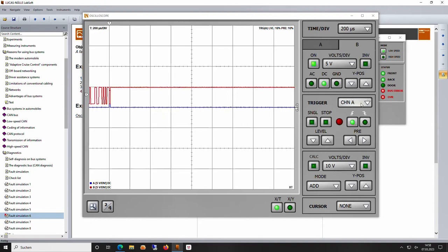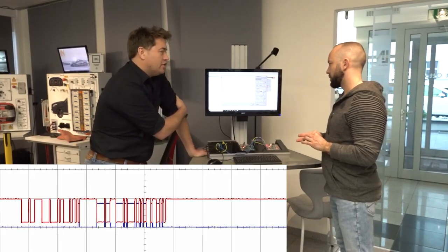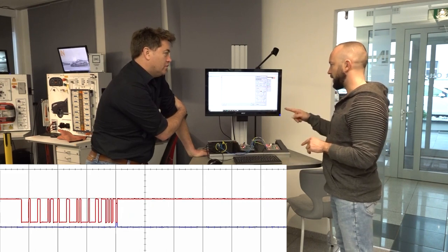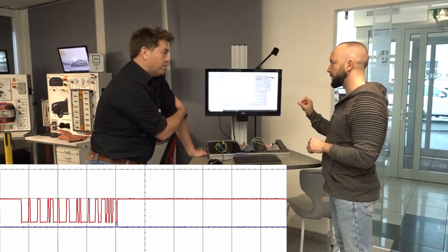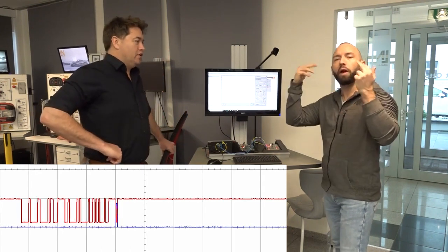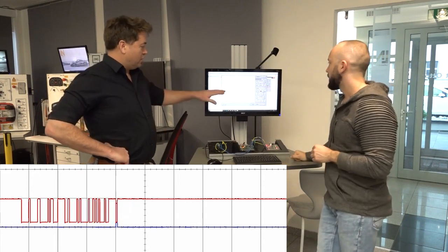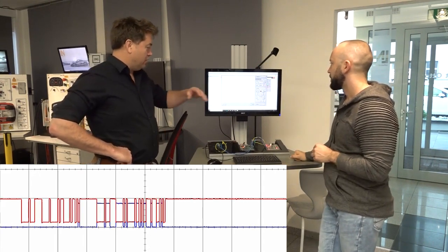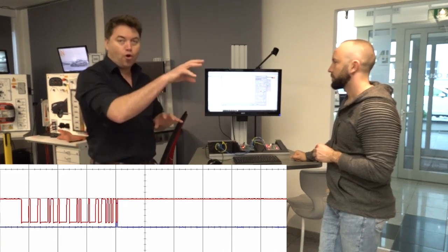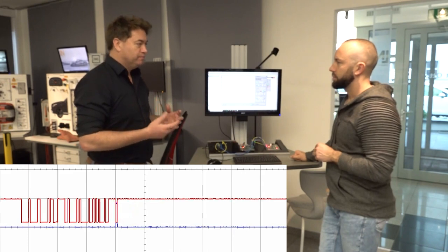This one here is also quite interesting. So this is showing that part of the CAN node has gone missing. Now this last piece, that's the acknowledge bit, is that correct? That's true. Yeah, we have the CRC and then there's the acknowledge bit, which basically says, yeah, signal not sent, but signal arrived, received, exactly. And so it was unable to, it said, yeah, we've got the signal, but it wasn't able to send the signal on. So there was one of the nodes in the network missing.